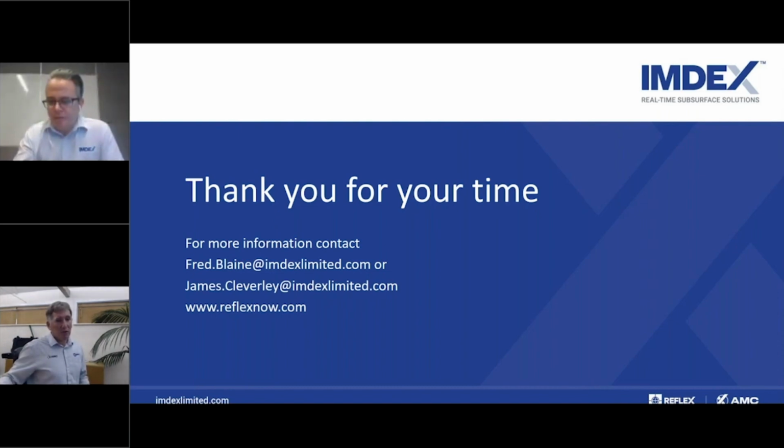Yep, gamma survey in rods, absolutely. The way this is done, Spiros, the beauty of natural gamma is it can be done in the rods without any real impact on the quality of the data. So it's a really useful tool, particularly in those zones where you might lose the hole. So it's probably one of the few data sets you can collect where you can't get a tool down open hole, you can get the gamma in the rod.